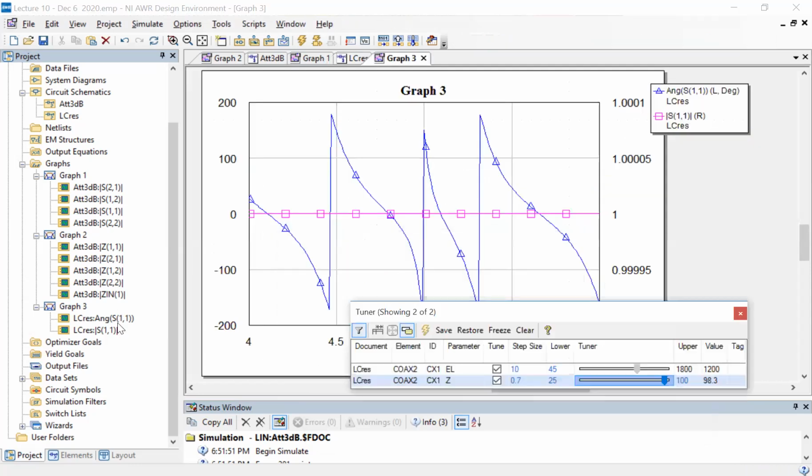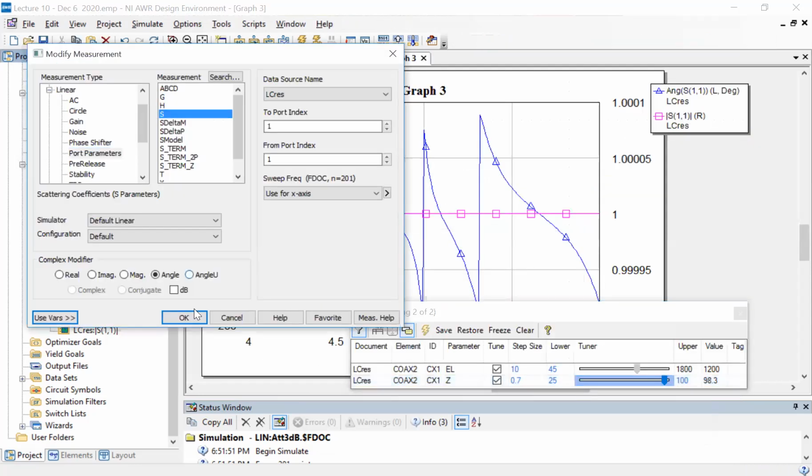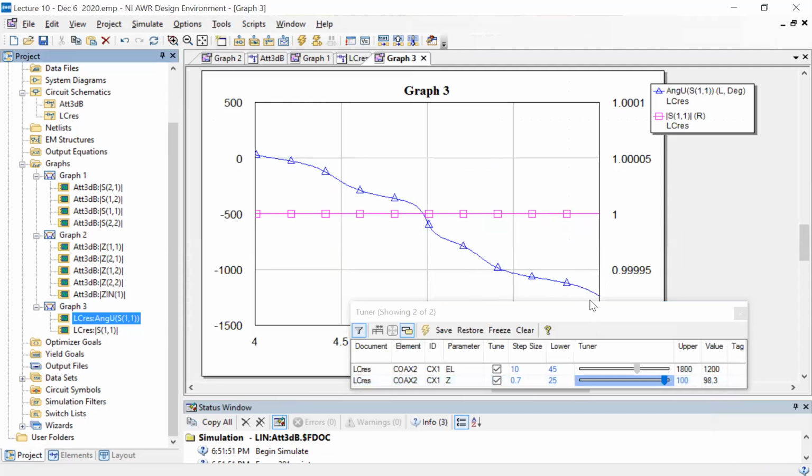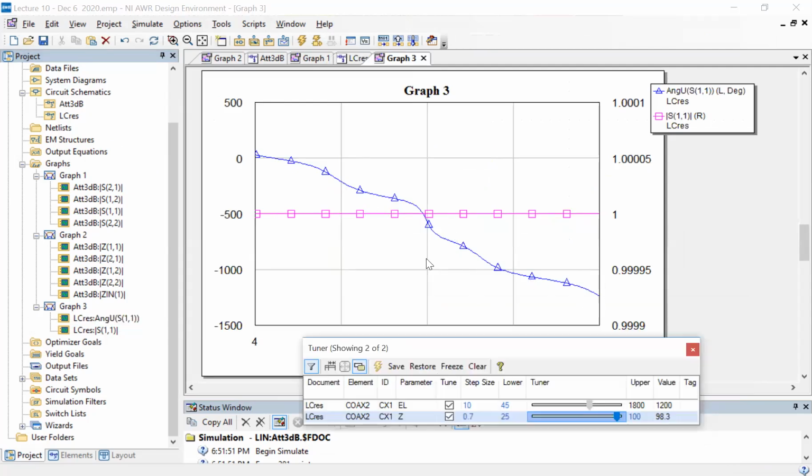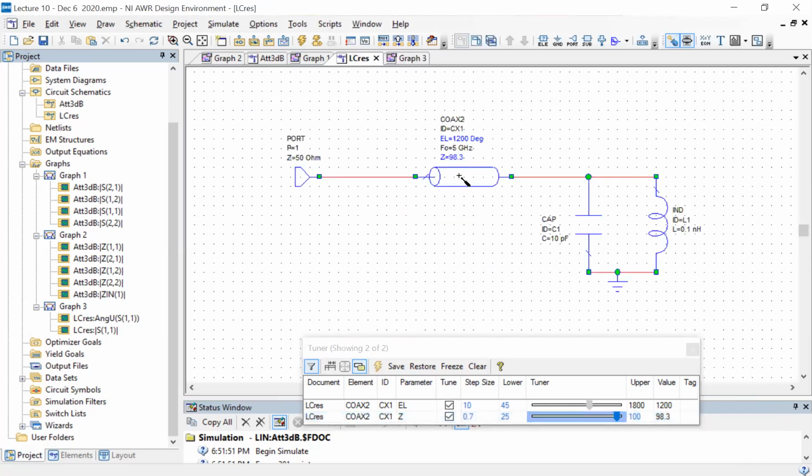So even if I did this angle U, this is how it looks. And this is quite typical. And in fact, Joydeep and Supriyo, you guys have done these measurements. You get all these weird ripples and other things which show up in your broadband phase response. And these are all essentially due to reflections. Here, this is a simplified model where I've made the transmission line different. This, of course, doesn't happen. You never end up accidentally using a 100 ohm transmission line.